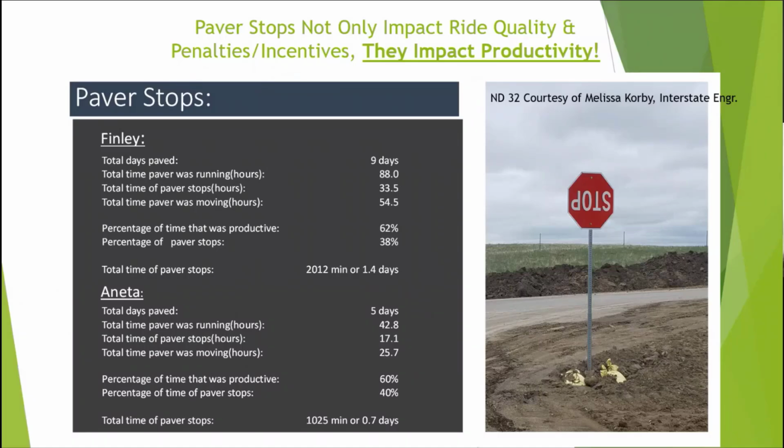It's the tortoise approach. A lot of times the correction for, in my experience, 70% of paving problems is to drop your paver speed down 8 or 10 feet per minute, and a lot of those problems go away. Now you have trucking issues and so forth, and trucks break down and pavers break down.